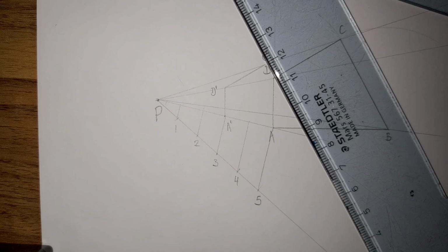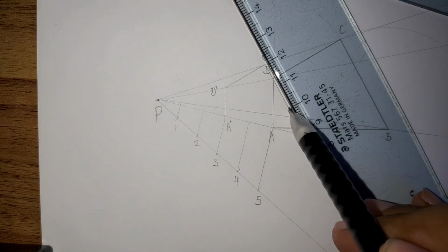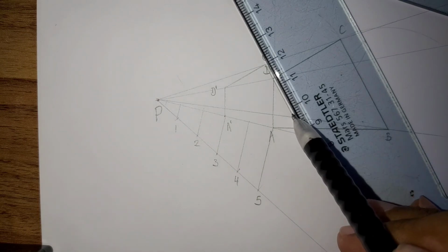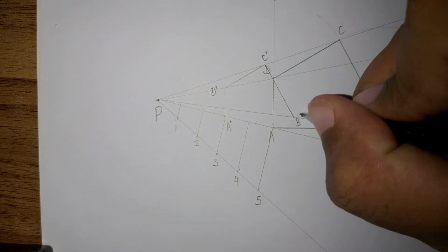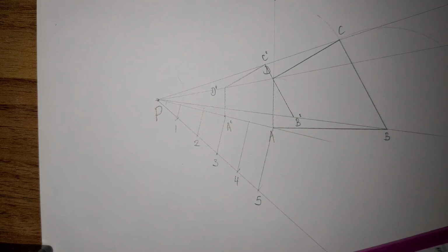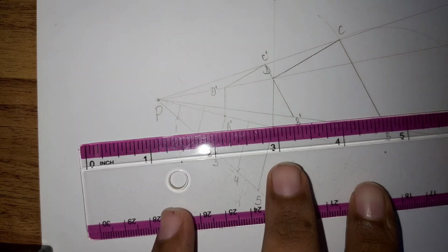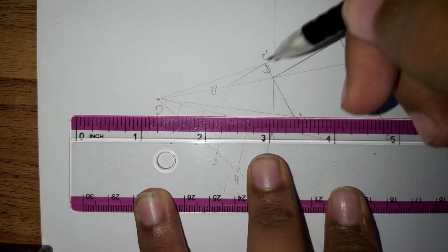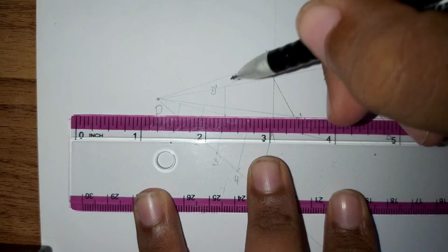And what you should be noticing is that the same line going through A1 goes through A, the same line going through D1 goes through D, and the same line that goes through C1 goes through C. So you can see that I've gotten the point B1 there, and all I need to do is connect A1 to B1, and that there is going to give you the reduced figure. That's how you get the reduced figure.